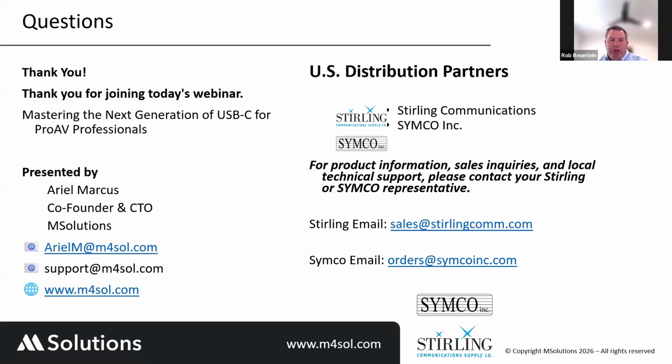Okay. We got one other question, and someone wants to know: does a cable that is 40 gigabits per second USB 4 rated pass DP Alt Mode? Yes, those cables can pass DP Alt Mode. Again, it depends on the capabilities, and it will come on top of the USB 3 capabilities that are running. Again, all the cables are structured the same, the USB-C, referring to cables, extenders, passive and active cables. The interface of the USB-C is the same.